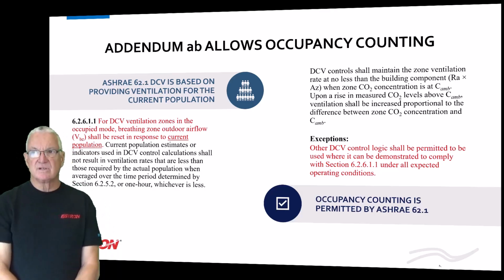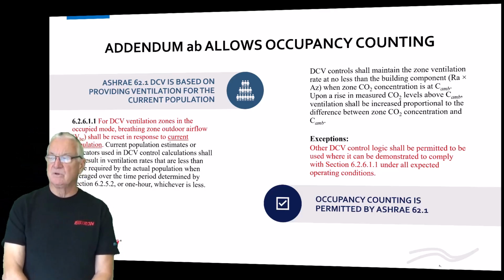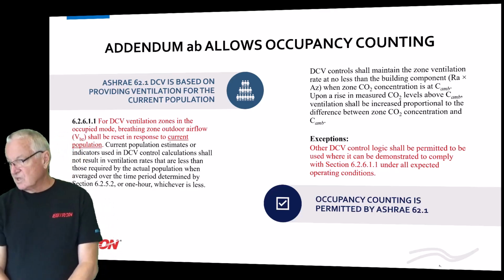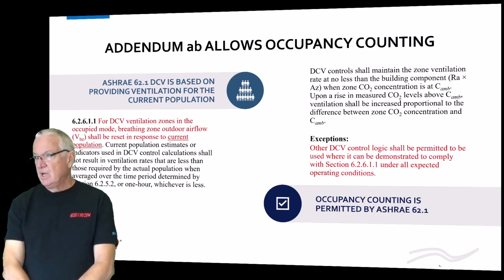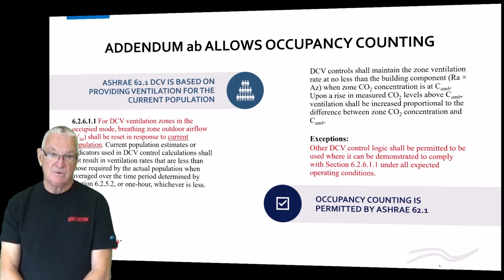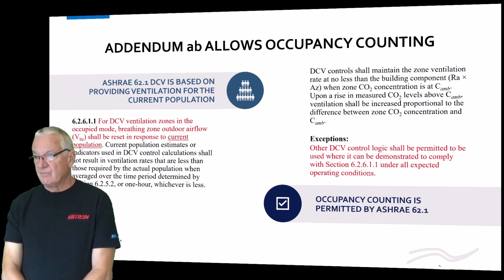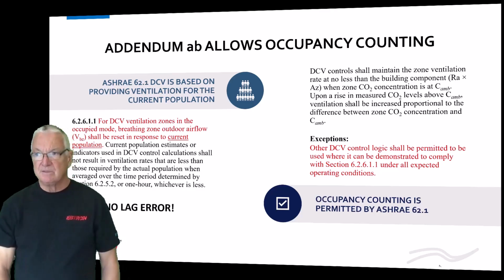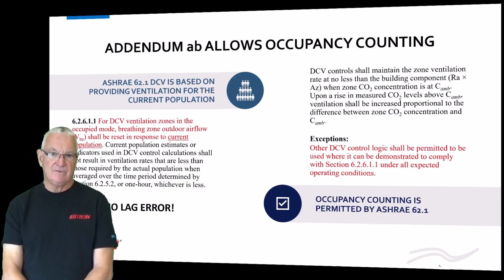Now, there's lots of different spaces out there where you can measure people. You can measure the occupancy of people going through the door. There's technologies available. We have one. There's other people that make them. I always tell people with things like movie theaters, where you have a point of sale system, it tells you exactly how many people are going into the movie, when it starts, when it ends. Tie that data into measuring the outside air and set the set point. There's no lag problem. There's no uncertainty problem like you have with the CO2.